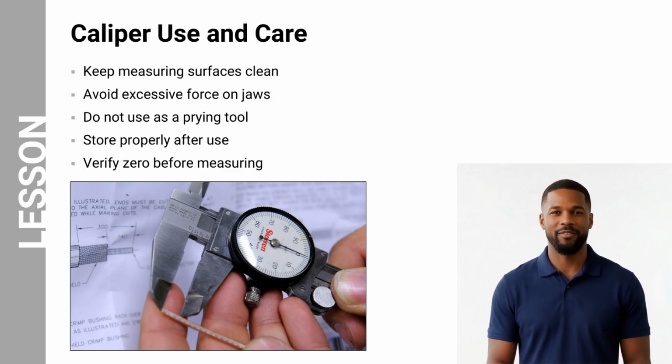Calipers should never be used as prying tools. This can permanently affect their accuracy. The tool must be checked for zero before each use. Proper storage protects the tool from damage.